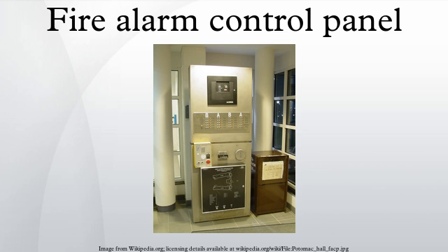Lamp test, also known as flash test. This button is known to have become obsolete, but is still used on many panels. This function is used to check the condition of the LEDs themselves. A lamp test button is required by code on multi-zone panels installed in Canada. Many panels do a lamp test when the system is reset.